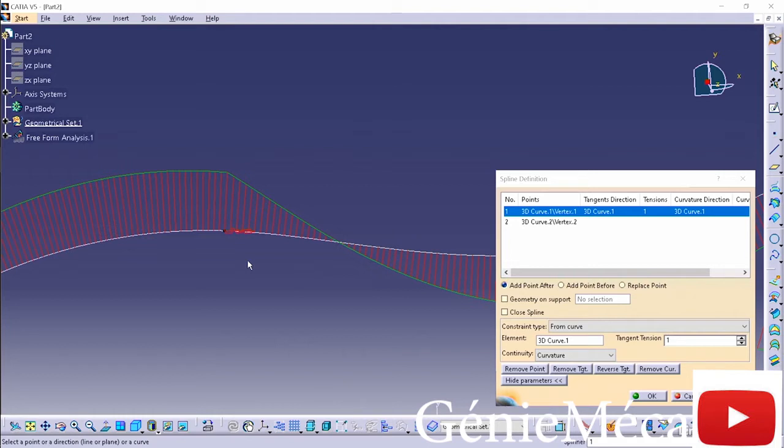And the same, again, is held true for surfaces. When you're doing surfaces on an exterior body panel, you may need to do things like accelerate that curvature. As you can see here, I'm accelerating it because I want even a smoother transition across that boundary, going into what's called G3. That G3 is the rate of curvature plus acceleration. So everything that you see on an exterior body panel with large flowing surfaces is going to have a G3 condition.